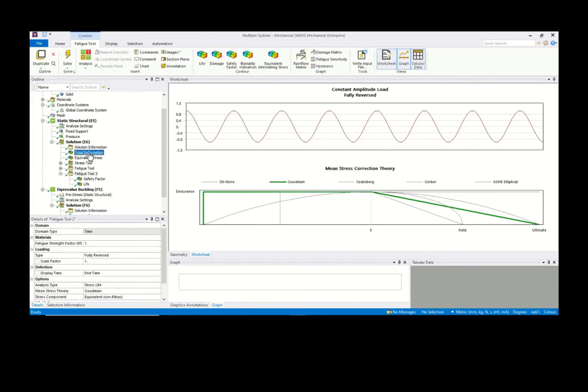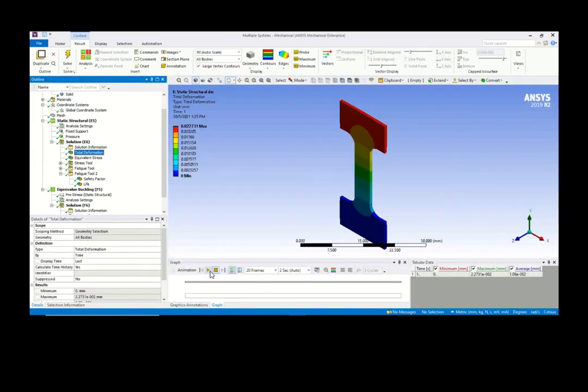Once you have solved it, you can get the deformations. If you can see, the bottom base is fixed, then you have 50 megapascal statically loaded, and you will see how it deforms. The maximum is here, around 0.022 mm. The stress induced is of course happening at this curve, where the concentration is, around 216 megapascal.